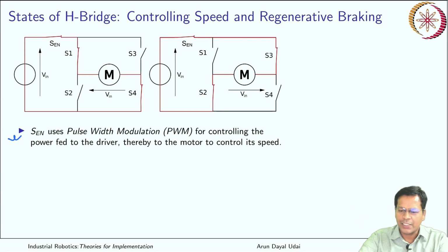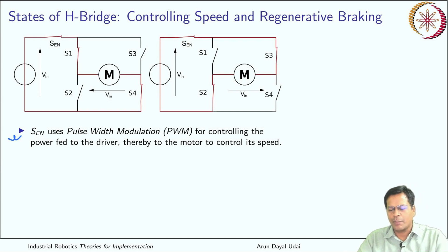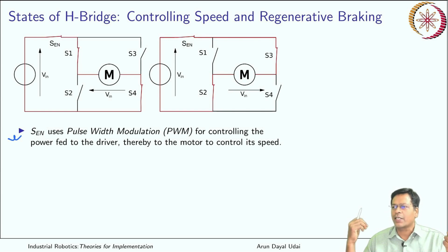But yes, that has a problem. Maybe at a very small amount of voltage, the motor is not running and current keeps on flowing through your coil. If it stays there for a longer period of time, what will happen? It will finally create a huge amount of thermal load, and finally it can go bad. So that is the reason you should avoid that.